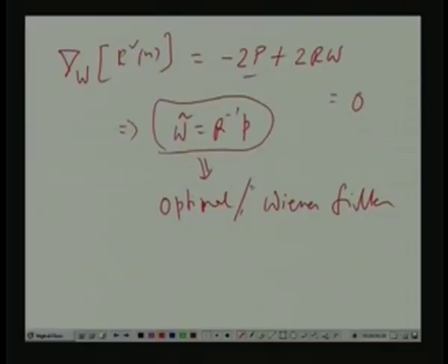You should try to have some adaptive mechanism by which your filter learns from the data that is coming in and tries to adjust itself by some iterative method, so that finally it converges on what should be the corresponding Wiener filter for a given R and given P. Then again, after a while, if R and P change, that adaptive mechanism will be used again.